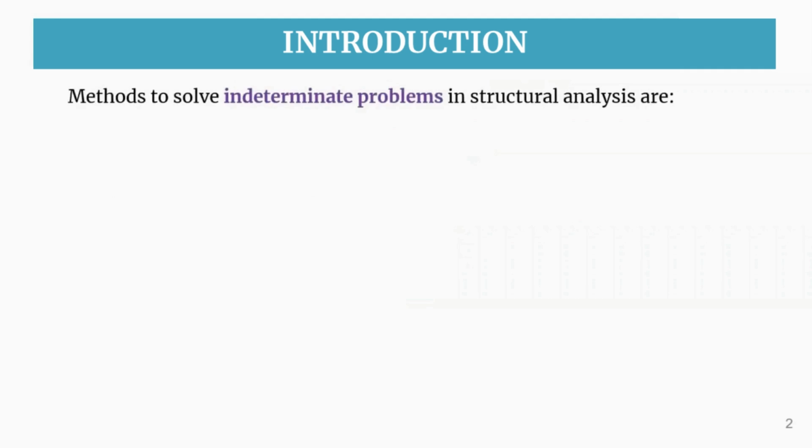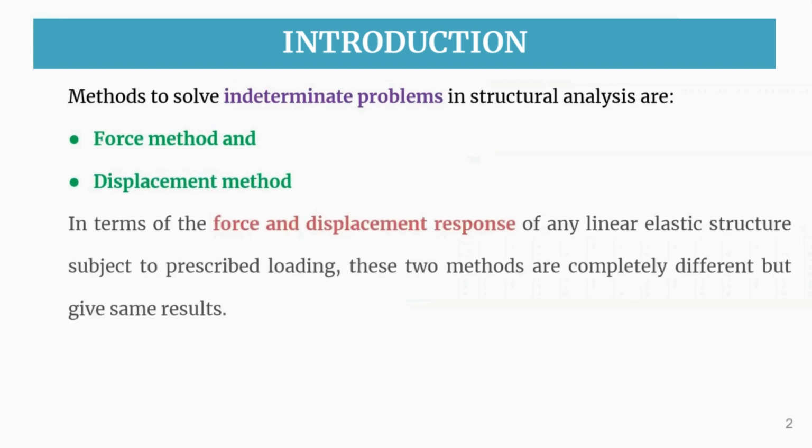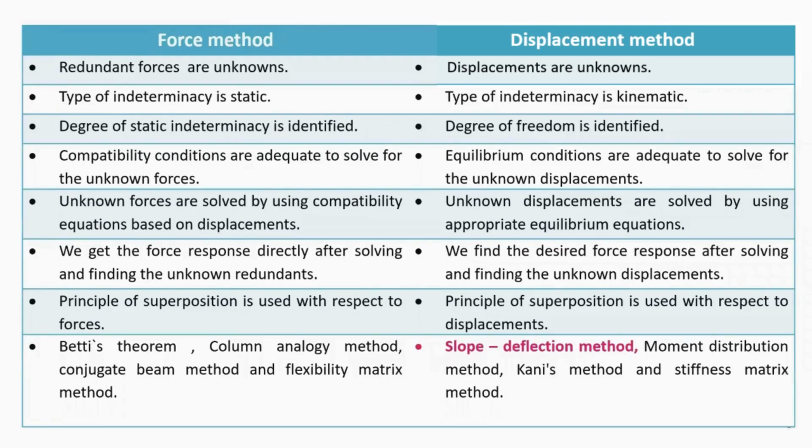So coming to the general introduction, there are generally two methods that are going to solve the indeterminate problems in structure analysis. One is the force method and another is the displacement method. For any linear elastic structure which is subjected to a prescribed loading, these two methods are generally used, but their approaches are different, but they give the same results in terms of force and displacement response. So these are some of the differences between the force method and displacement method.